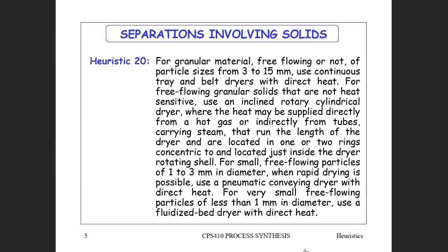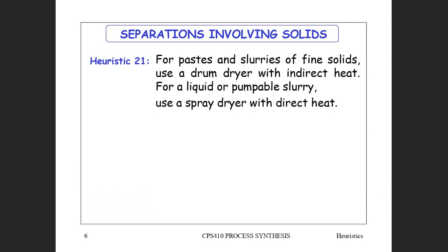All right, thank you. Can we move on to heuristic 21? For pastes and slurries of fine solids, use a drum dryer with indirect heat. For a liquid or pumpable slurry, use a spray dryer with direct heat.